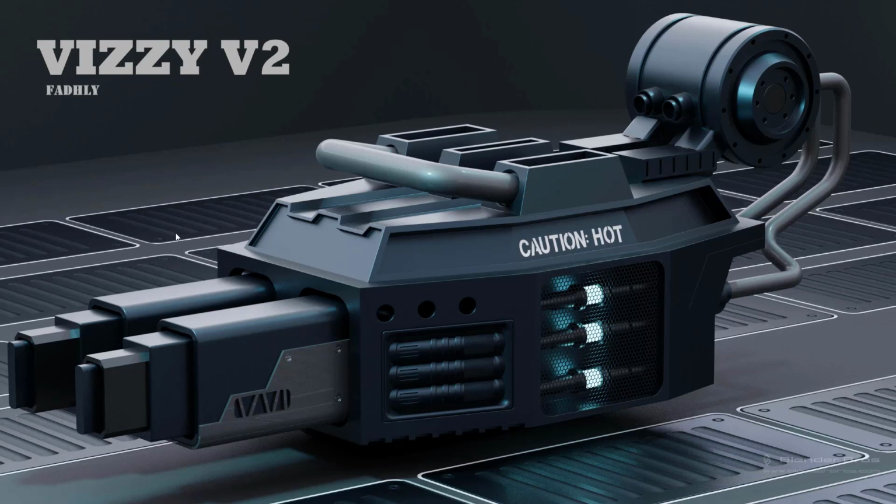And these decals on the floor here, I think you said you used Decal Machine. Go to the match button in Decal Machine, swap that white to a different material so that it doesn't stand out. I really don't like the white borders on here, it doesn't match at all. So basically switch these white ones to a different material, maybe match the gray floor here. It should allow you to do that. If it's a subset decal, you just shift click, press the D key and then shift and scroll, and it'll let you switch through on the secondary material.